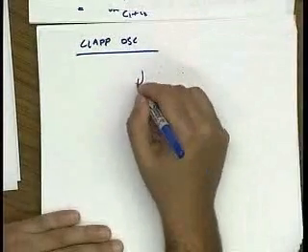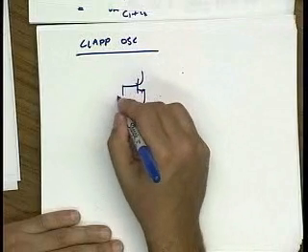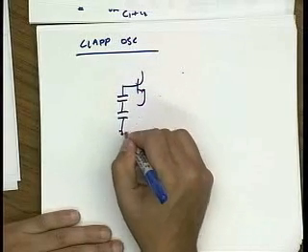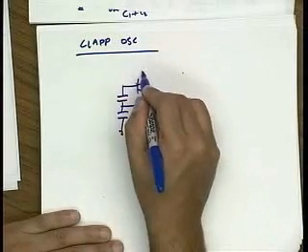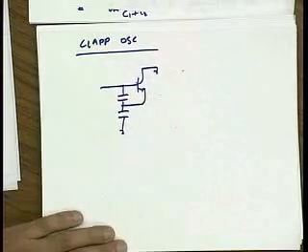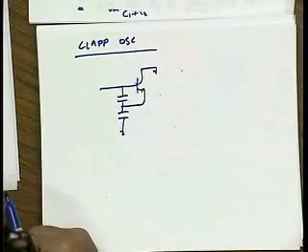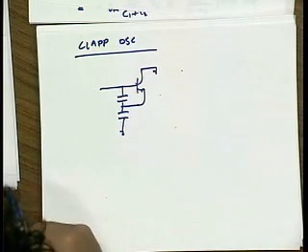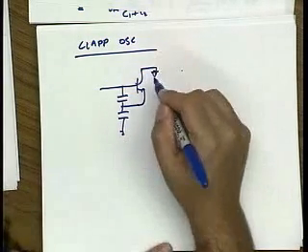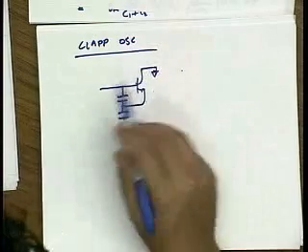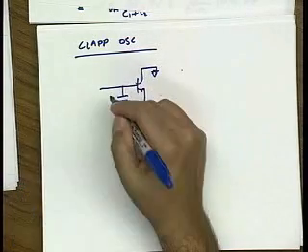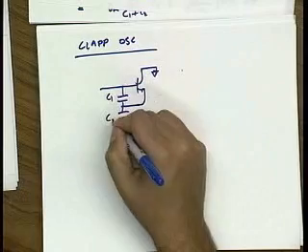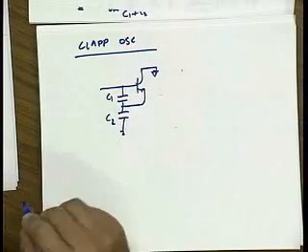So the Clapp oscillator actually, in some ways, is kind of mysterious, right? So if I look at this circuit, it's not very obvious where the loop is, right, and what the loop gain is. If you follow the procedure that we used last lecture, you can exactly calculate all the parameters for the circuit, the loop gain, and predict the oscillation amplitude.